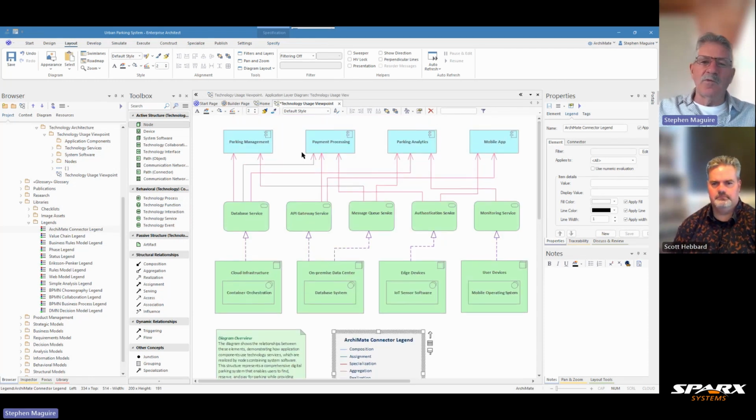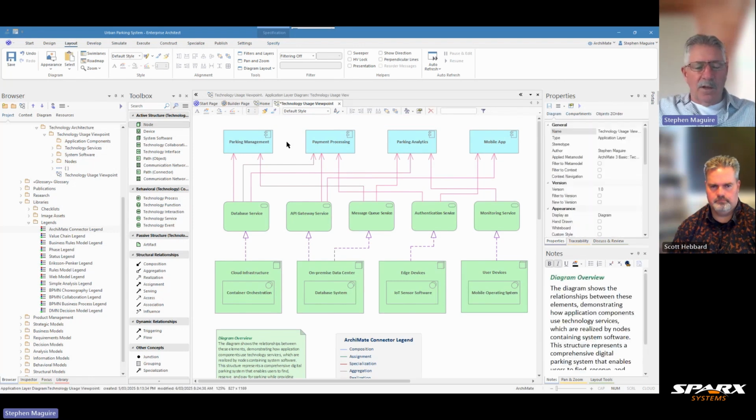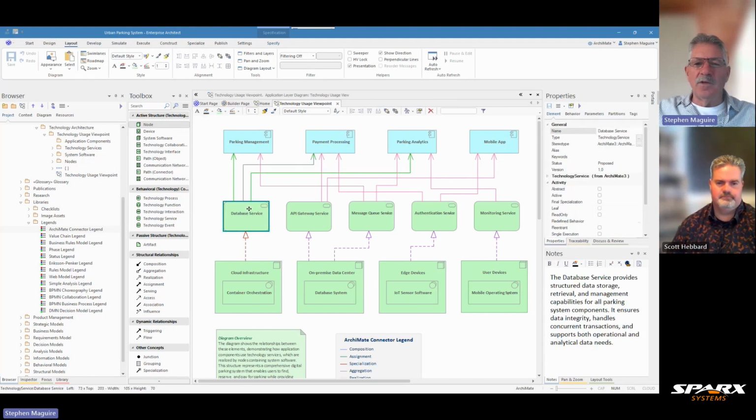All those lines are crossing over there. It can be a little bit difficult to understand them. What we can do is use some of the things on the layout ribbon and the helper panel here, and I can say select presentation there and select show direction. Let's have a look when I select an element now. You can see just the lines colored that are the outgoing and incoming lines on this element. So the different colors, the red and the green, are representing outgoing and incoming connectors, and that makes it very easy to see which lines are which.